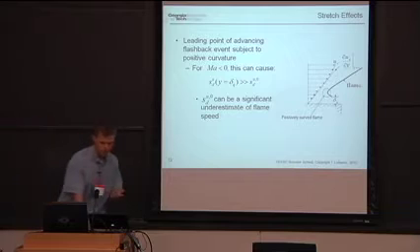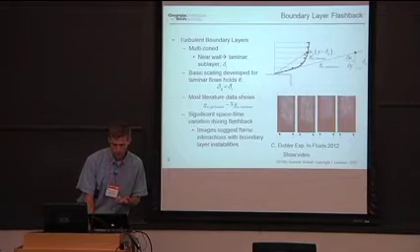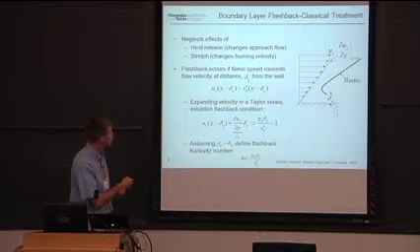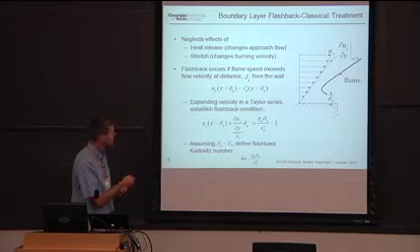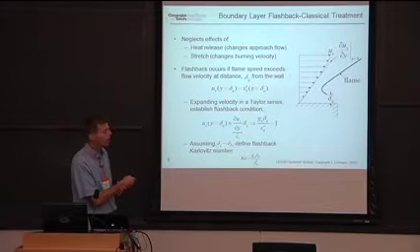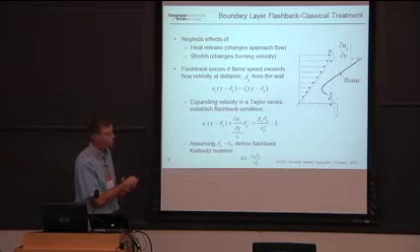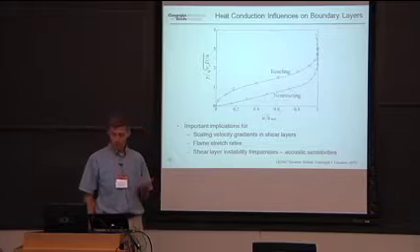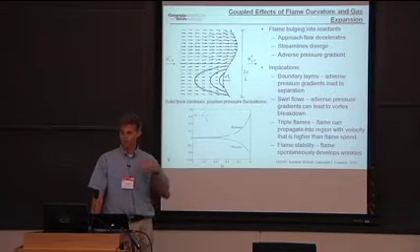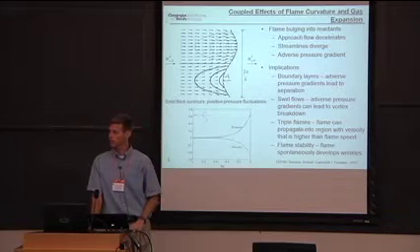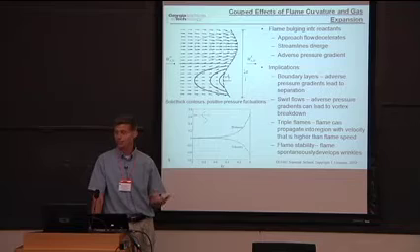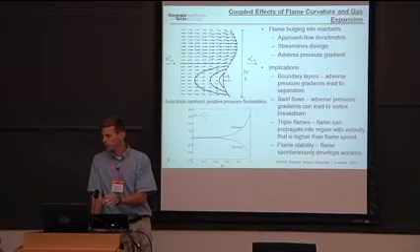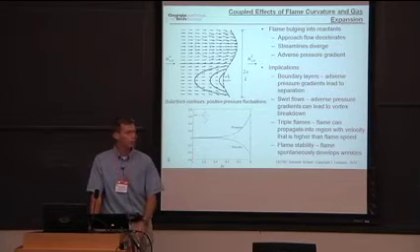Okay, so I've talked about, let me just back up for a minute. If you neglect the effects of heat release and stretch, you impose the velocity and you know what the flame speed is. So I just told you that in reality, you don't know the velocity because it's a coupled part of the problem. Now we can talk about the burning velocity, the flame speed. That's also part of the problem. If you have a flame that's stretch sensitive with a non-zero Markstein length, that's also going to affect the problem. And in particular, since the leading point of the flame is positively curved, we care about the sensitivity of flames to positive curvature. And in particular, if you have flames with negative Markstein lengths, what does positive curvature do? It accelerates the flame speed. So what kind of fuel has negative Markstein lengths?